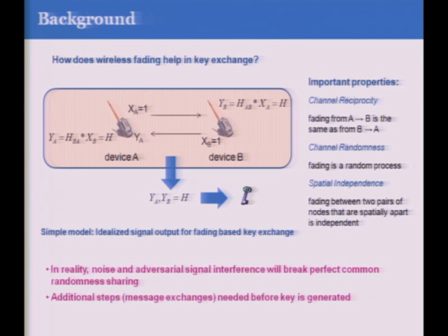I think what people have shown is that if you're just a few wavelengths away, then the channel completely becomes independent. And a few wavelengths, when we're talking about gigahertz, is just a few centimeters. I see. You really have to sit right there. It depends on your modeling assumptions. If this is in free space, you have absolutely no privacy, no security. But if you're in a wide sense stationary Rayleigh channel, then it is directly related to your wavelength, because there are assumptions on the richness of the scattering environment. Yes. So the idea is that there are a lot of scatterers around.